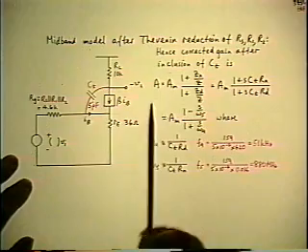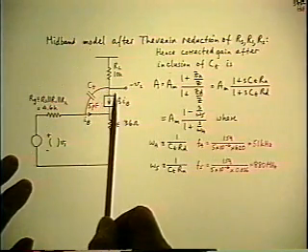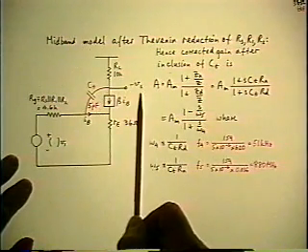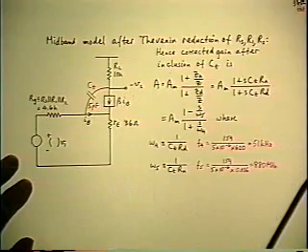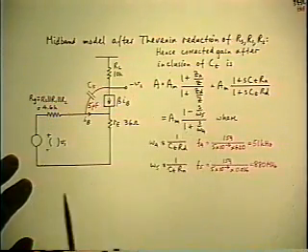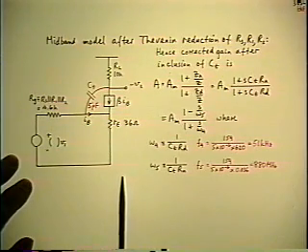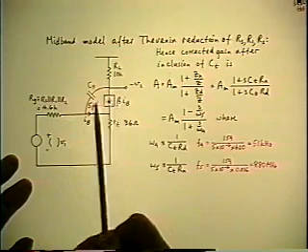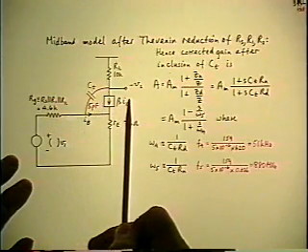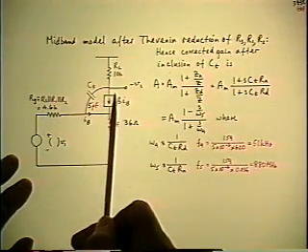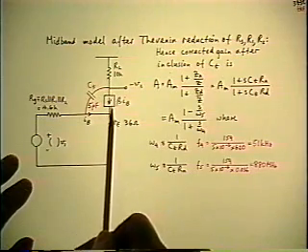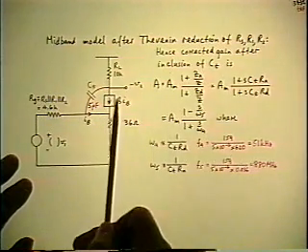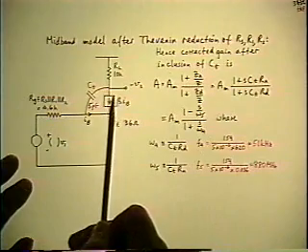But it has a parallel path through the CT, which is a non-inverting path of low gain. So it's exactly that block diagram setup we had earlier on. And so at low frequencies, the high gain inverting path through the transistor dominates, but the capacitor causes a low frequency pole and it loses its gain, which we haven't talked about yet. It's part of the answer.